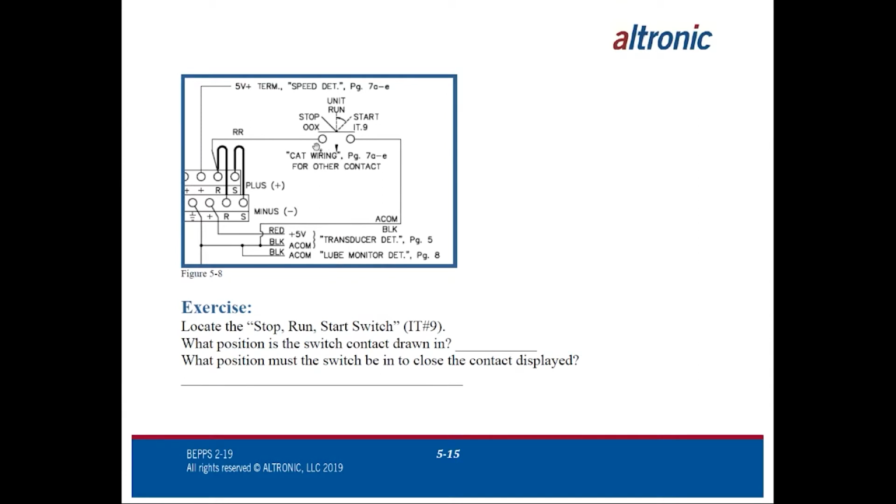So using a known voltage source with your meter and coming with your negative probe to take measurements that complete a voltage path or voltage circuit is a great way to troubleshoot circuits rather than using what a lot of people want to jump to as an ohm meter.